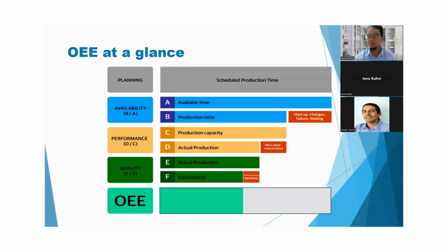Try to eliminate your wastage, or you can try to reduce it, or try to eliminate it completely using a lot of RCA tools like 5 Whys, FMEA, fault tree analysis, Ishikawa. And then you give those projects to your engineers to reduce it, to ensure that your OEE is going to increase after some time. That's the idea on this OEE system.